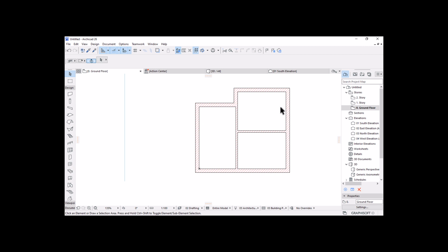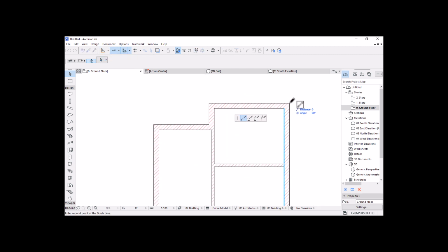So to fix that, I'll draw a guideline here using either a line tool or a guideline. There is what you call a guideline, which is this tool in ArchiCAD. So we can come here and then click on this arrow, and then we can say create a guideline segment, or hit Alt L. Alt plus L is the shortcut for this command. So click on that, and then I'll draw a guideline from here going all the way to there, and this should be a 3.9 guideline.